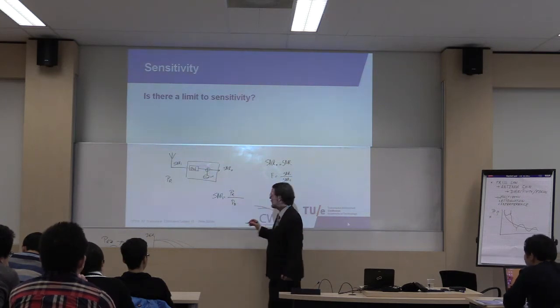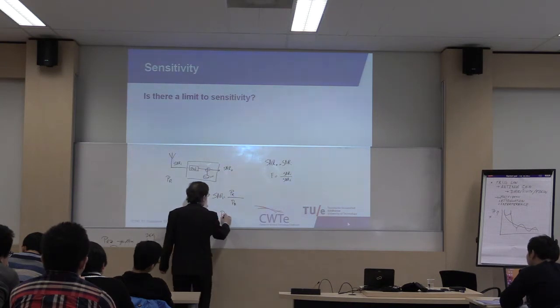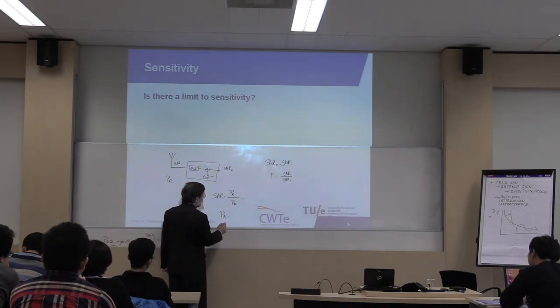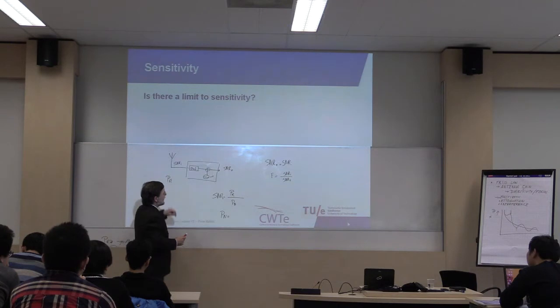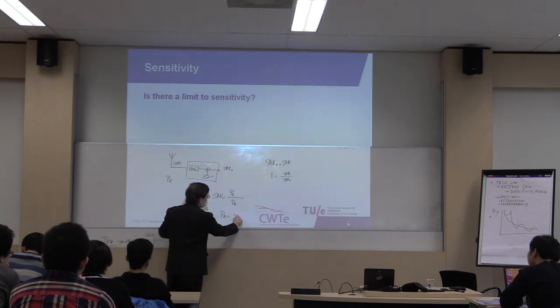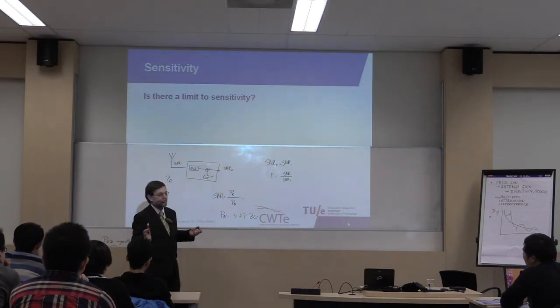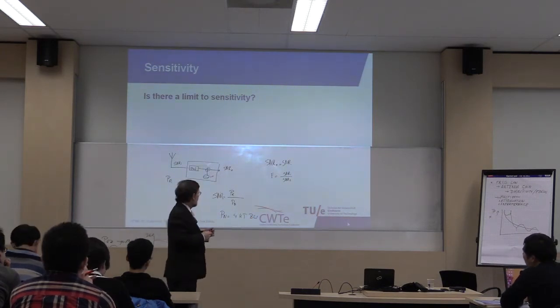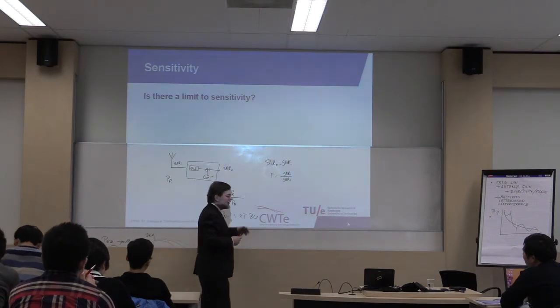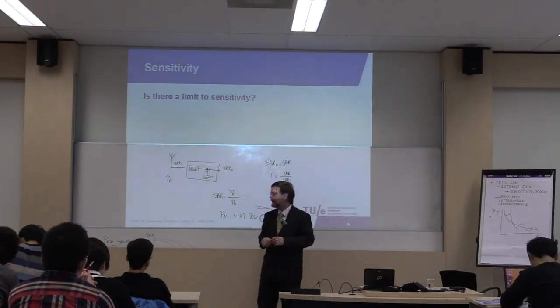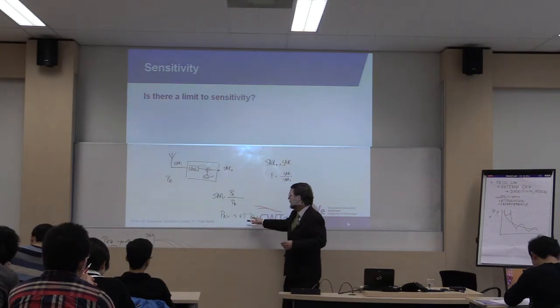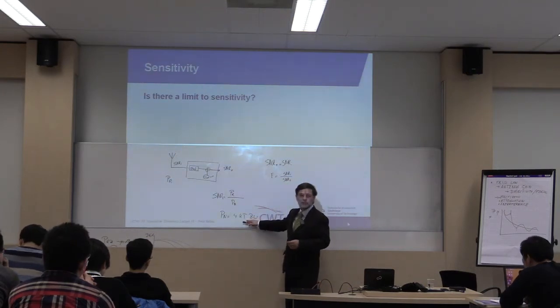And the nice thing is that the noise power at the input for any radio that only has thermal noise, so any perfect antenna, gives you a noise power of 4kT times the bandwidth. That's all the noise you get. And you can see here if the temperature would be zero, I would get rid of that noise, but that's not the case. You have to keep in mind that this is the temperature of the object that the antenna is looking towards.